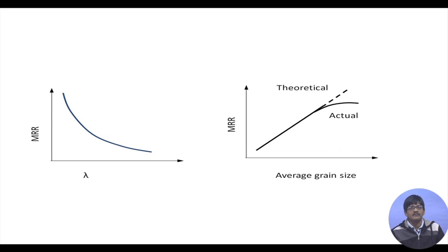Therefore, the tool will take up most of the damage, and therefore MRR will be coming down. So, that is what is reflected. Tool will be taking up more of the damage, delta T will be much higher than delta W, and therefore MRR will come down. MRR essentially refers to the material removal rate of the workpiece.